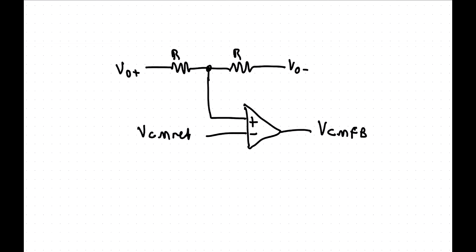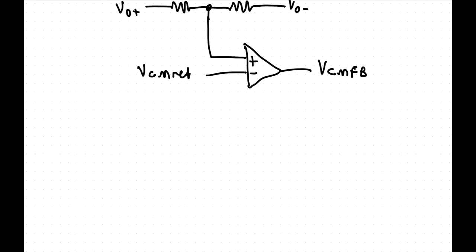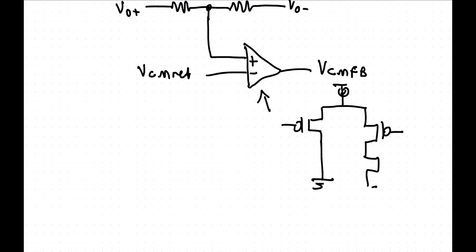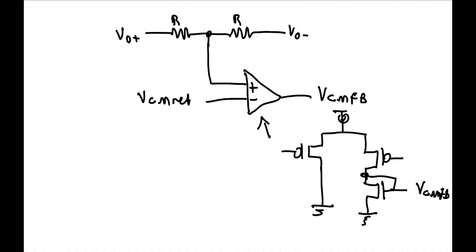Okay. Now that amplifier there doesn't need to be complicated. In fact, having a simple amplifier is really quite good. I would probably make the amplifier here a differential pair, PMOS differential pair like that. And then one of them I'll just dump to ground, the other one I'll put into a diode connected transistor, like that, and that will be my common mode feedback, like that. So then what is plus? If this is higher, that's going to be plus and minus like that.